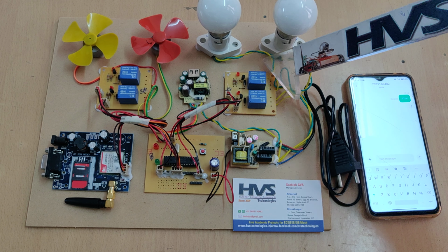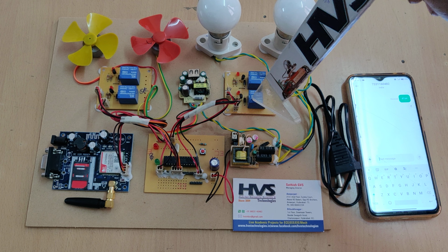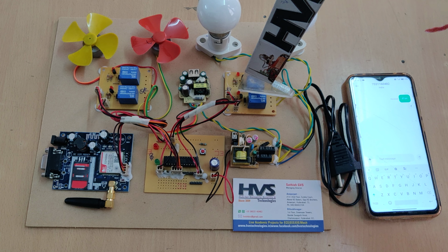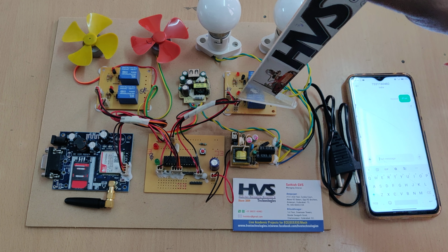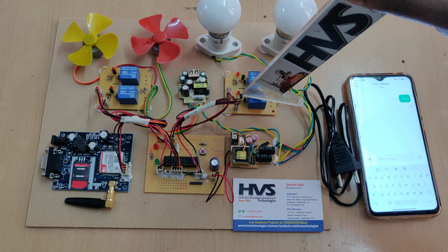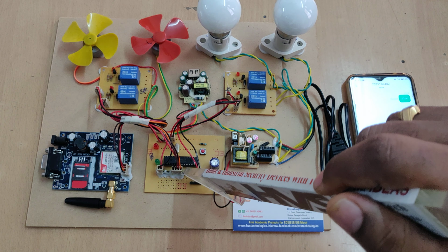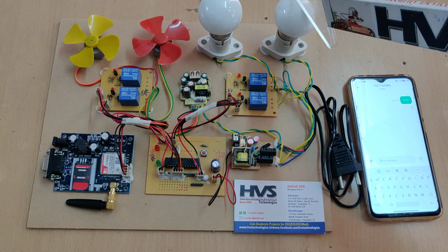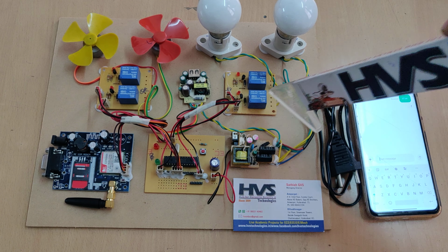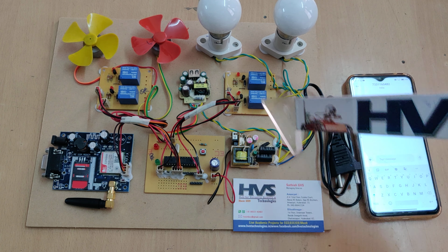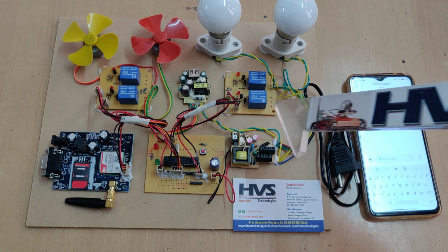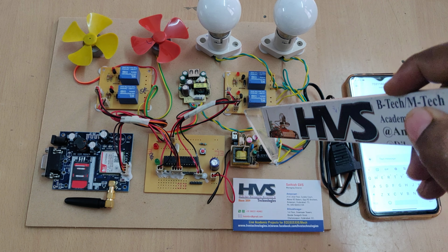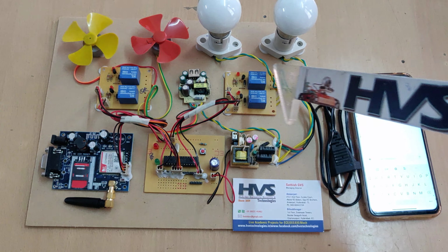And coming to this relay board, we can see the same kind of circuit diagram for each relay. In one circuit diagram, there is one LED which shows the status of the relay, with a 330 ohm resistor, and a BC547 transistor. Here the microcontroller will trigger the transistor, the transistor will trigger the relay, and the relay will trigger the bulb. So this is the switching flow. And here one more diode is there. The purpose of the diode is to act as a freewheeling diode. Whenever the relay is switching on and off, it produces a back EMF that will be neutralized by the reverse bias connected IN4007 diode.